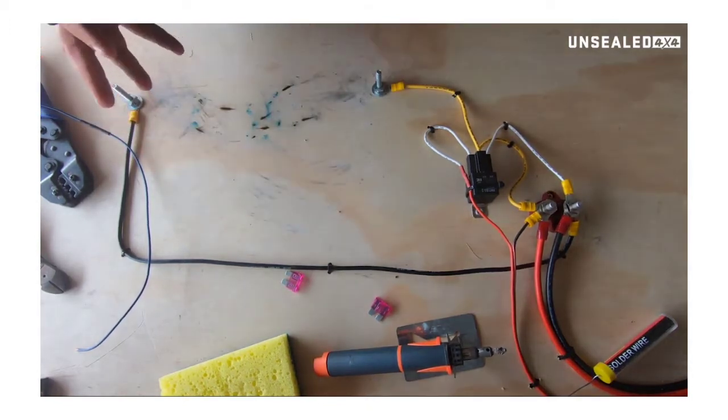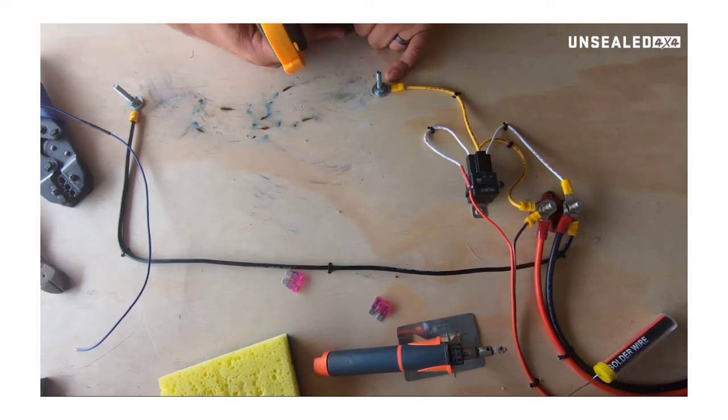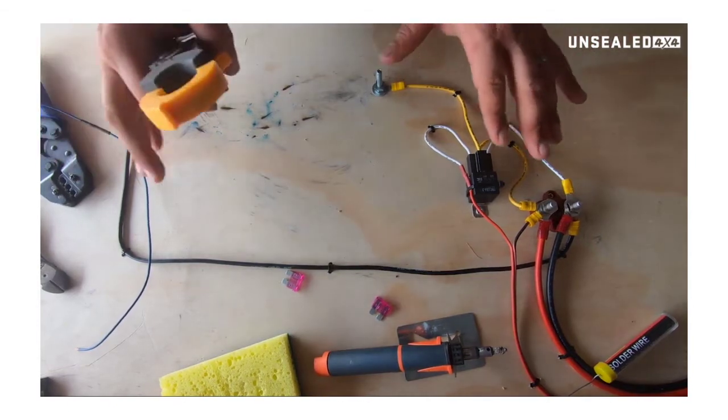Right, so with a normal multimeter, you have to put one terminal on here and the other one on the light, up to a maximum of 10. And the problem with doing that is if we're drawing more than 10 amps, we can blow the multimeter up or the fuse in it. And then you've also got to break the circuit. Whereas with this one, we could have the connection already done, right?